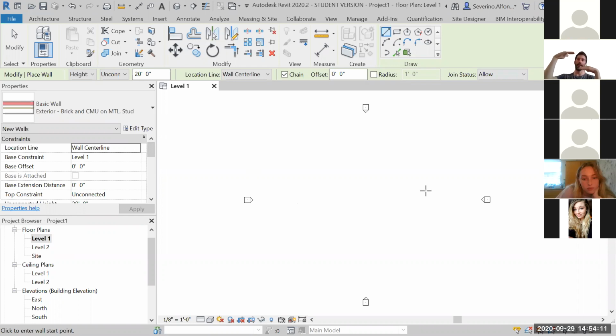That's the way I control the height. Is it going from level 2 to level 3? Imagine you have a building with 10 stories. Maybe you want to say this wall goes from level 8 to level 9. And we'll talk about levels in a second. But you need to say from where to where it goes, and all of these parameters up here are just to say that. You can use also these parameters. But let's just say I want the height to be up to level 2. This is what I just said here.